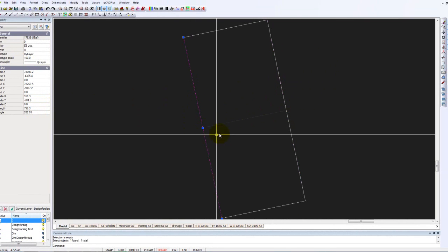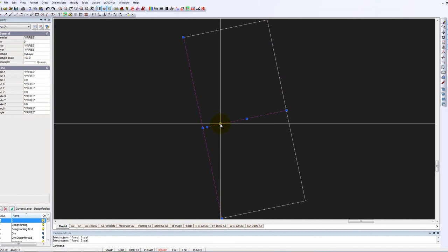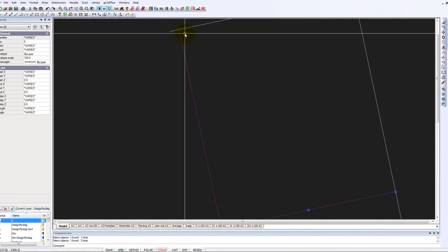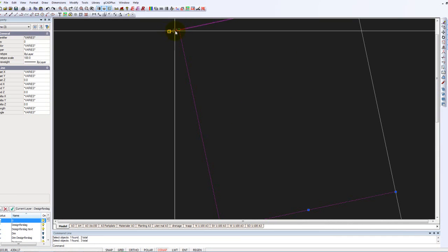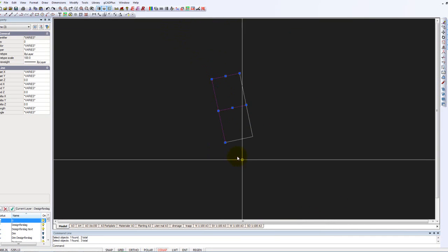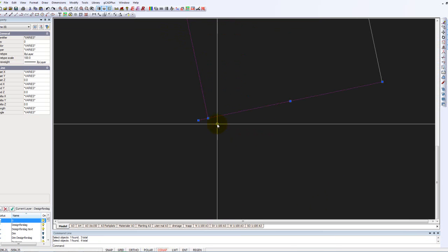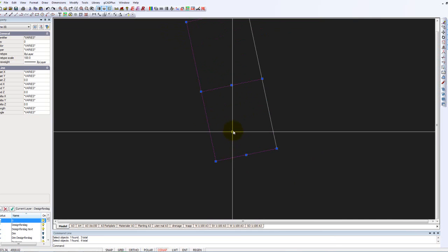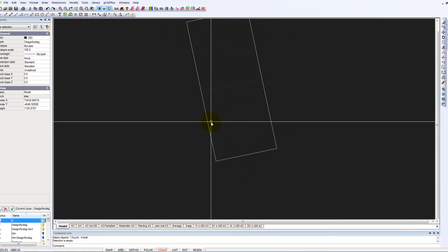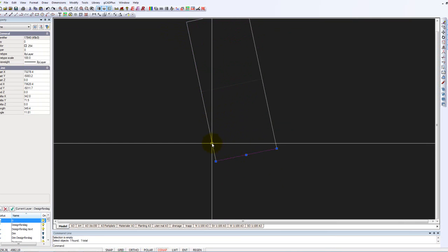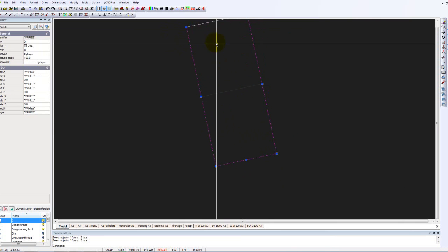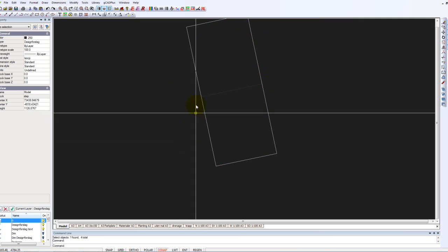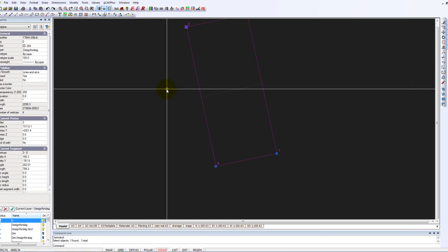We could pick this line here and the construction line that's been drawn there, move the midpoint there and snap to there, come in here, pick the edge, come back there to there, and through here we could pick the bottom line and bring it into position as well. So now we unselect all. We can pick the 4 lines that make up the block in that fashion, and we could right click and join them. Now it's one polyline defining the step.